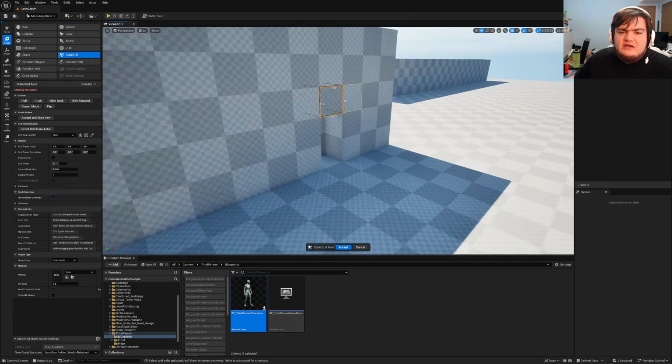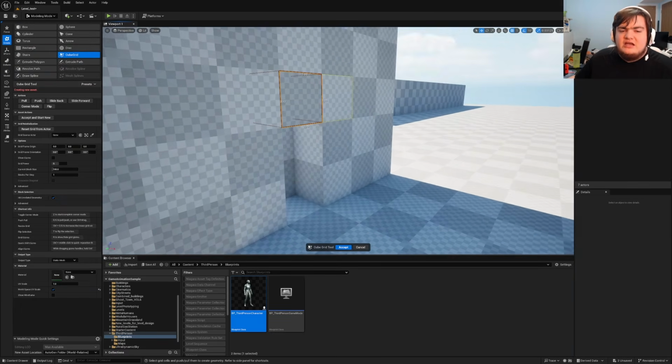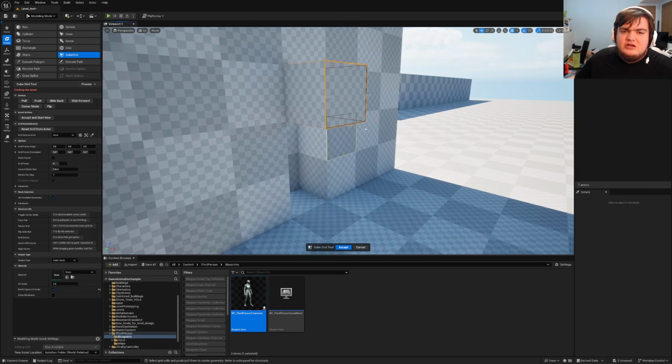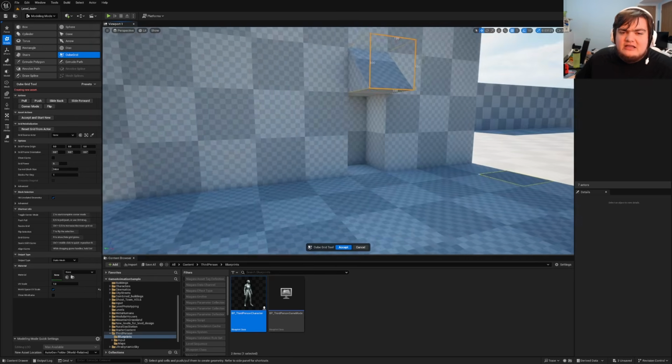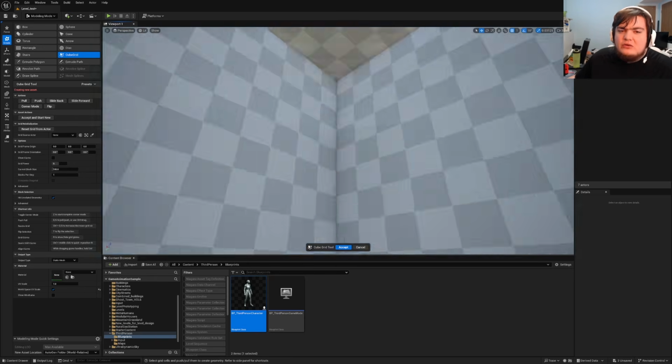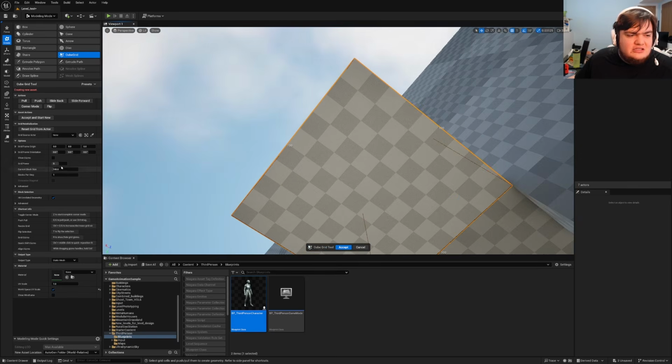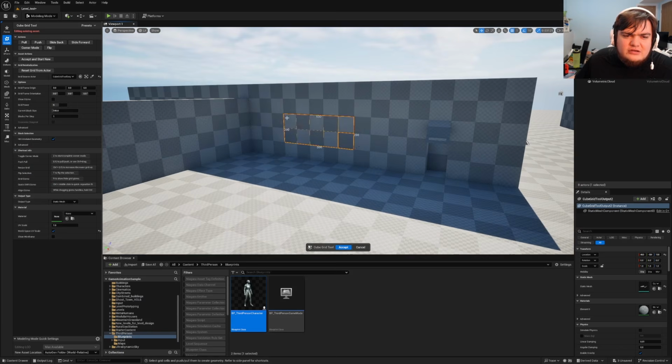What if we want a little spot for them to sit under in the rain? I can click here, hit E to bring it out, press Z, and click these little circles that show up on the corners, and I can hit Q to bring it back. And now we've created this little area that sits over the door for the rain. So we're going to use this to scale down the grid. Put a big old window right here. Maybe it's a bit of a fancy window.